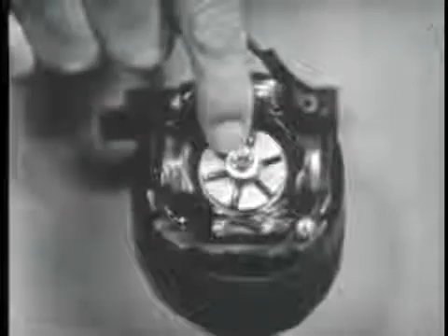Right. Okay, so the rotating magnetic field then induces a voltage into the conductors of the rotor, causing it to become an electromagnet. It exhibits a north and a south pole. The rotor turns at some speed determined by the load, both internal and external load. Now, the difference in speed between the rotor and the magnetic field is called slippage. All right? That is the AC induction motor.